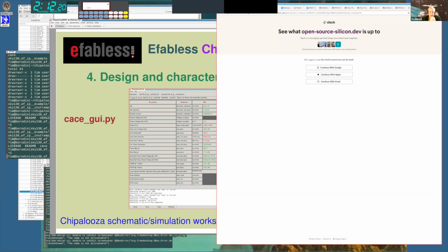The combined models are probably better overall just because the other models are discrete, and it's very easy in analog design to run into a problem where you have created a MOSFET that is just the wrong size and it doesn't fit in a bin, and then you try something like a Monte Carlo simulation or mismatch simulation and it says it can't find the device, and then you're left wondering why. You'll have much fewer of those kinds of problems if you use the combined models.